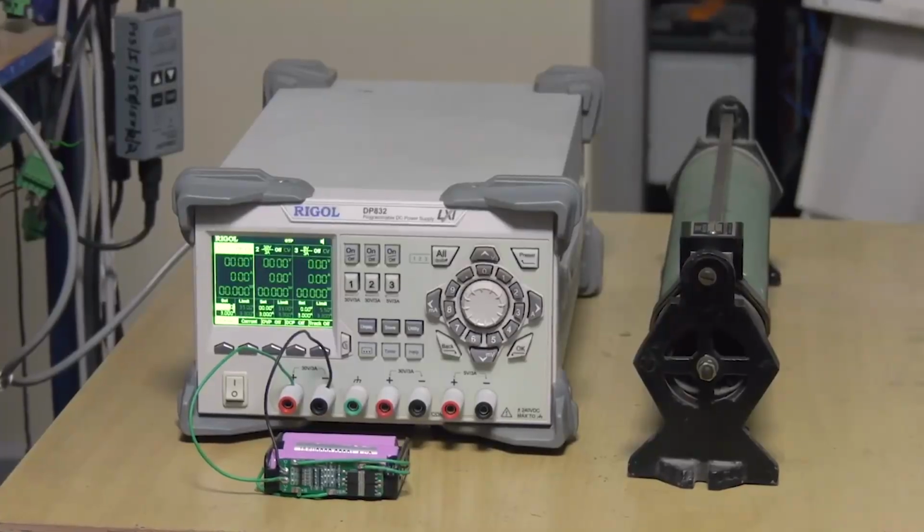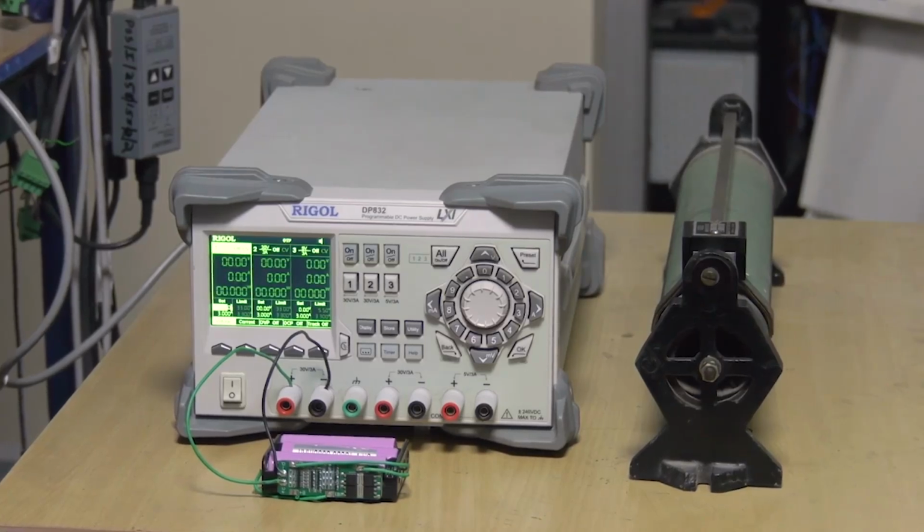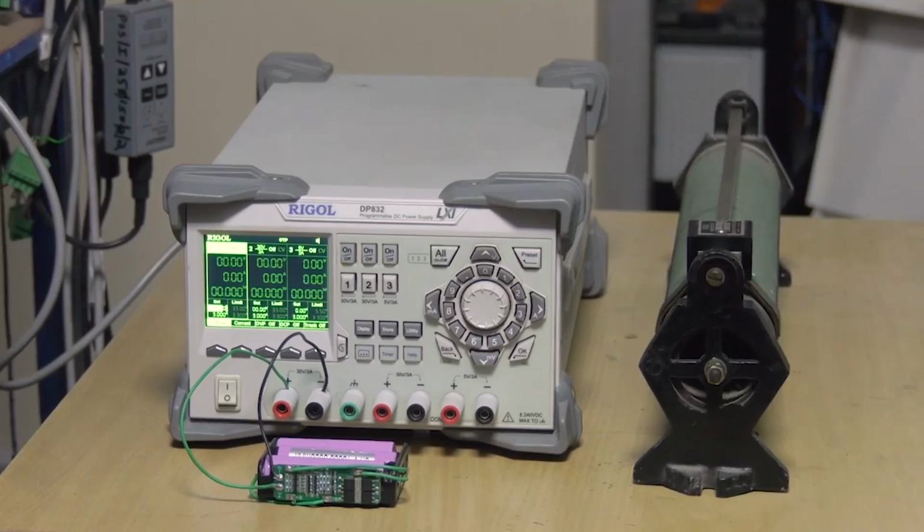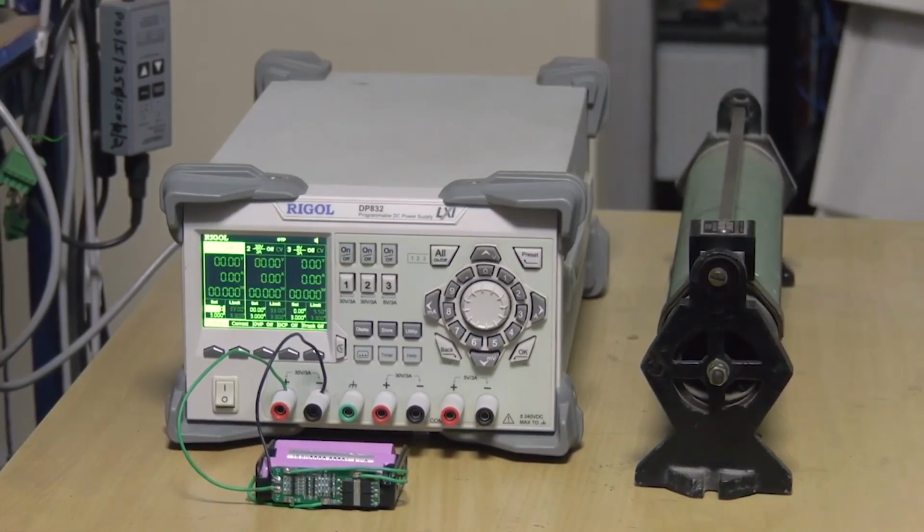This experiment aims to demonstrate a simple passive balancing for the charging and discharging operation of 3 lithium ion batteries through a readily available balancer IC. The bleeding resistor present in the IC allows the charge of the higher capacity cell to deplete through this resistor for both charging and discharging operations.